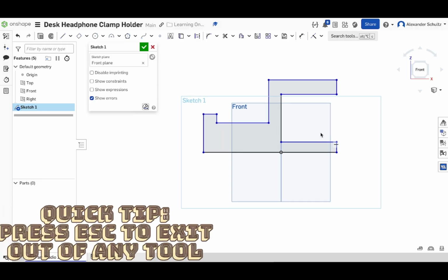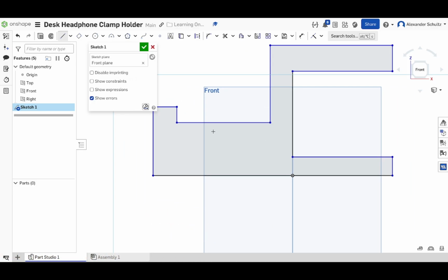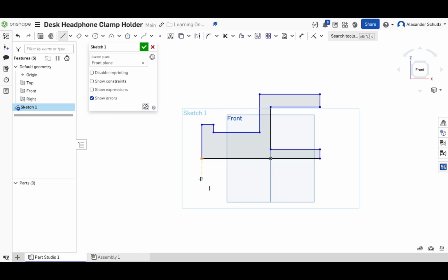Yeah, okay. And you probably could have, or maybe were able to tell when I was placing lines that you could see these dotted lines showing up, and then my cursor snapping into a position. That's what's called auto constraining. So you can see how these lines, when I hover over them, there's this little box that shows a horizontal line. That is a horizontal constraint that was applied automatically. Horizontal constraint is what you think. When you apply that, it will make the line exactly horizontal.